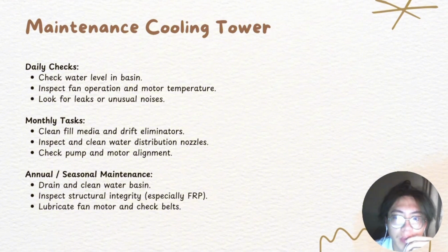Meanwhile, for the monthly task, clean fill media and drift eliminators, inspect and clean water distribution nozzles, and also check pump and motor alignment. For annual maintenance, we need to drain and clean water basin, inspect the structural integrity, especially FRP, and also lubricate fan motor and check valves.